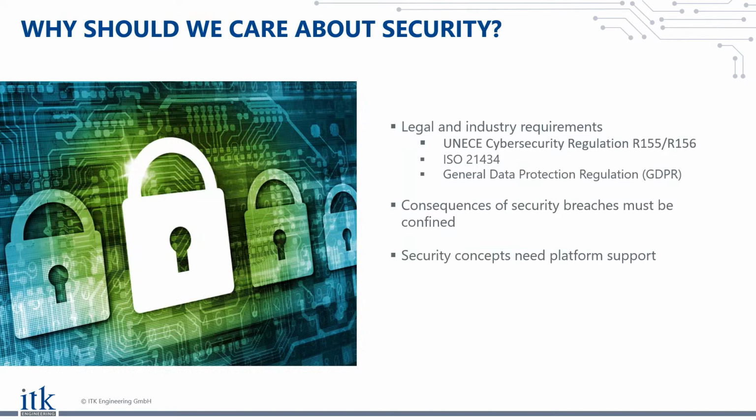Why should you reconsider security, or why do you have to consider security at all? Of course, there are some legal and industry requirements nowadays. Besides your motivation to keep your ECU secure, you have to fulfill some regulations, and you will have problems getting through software development projects and ECU projects if you don't have security engineering processes established. This is based on the UN ECE cybersecurity regulations 155 and 156, and strongly coupled to that, ISO 21434.